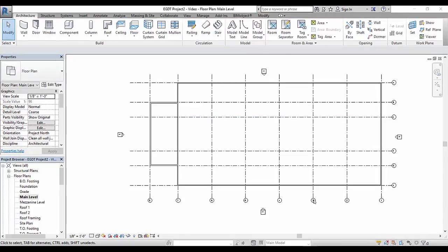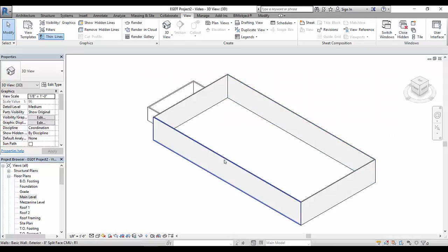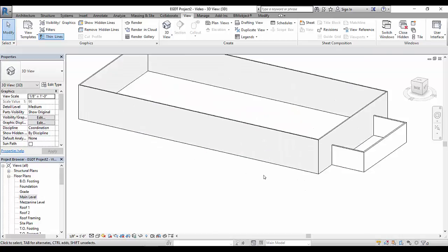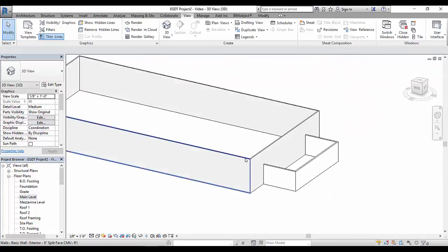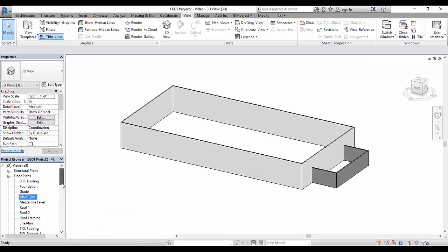Let's go ahead and take a look at this in the 3D view. So I'll go to my View tab here and select a 3D view. And if we look at our office and warehouse area, we have walls that are 26 feet high for my warehouse, 15 feet high for my office area, and it looks like everything's coming together quite nicely. I'm going to go ahead and change my visual style to consistent color so it stands out just a little bit more in that 3D view.